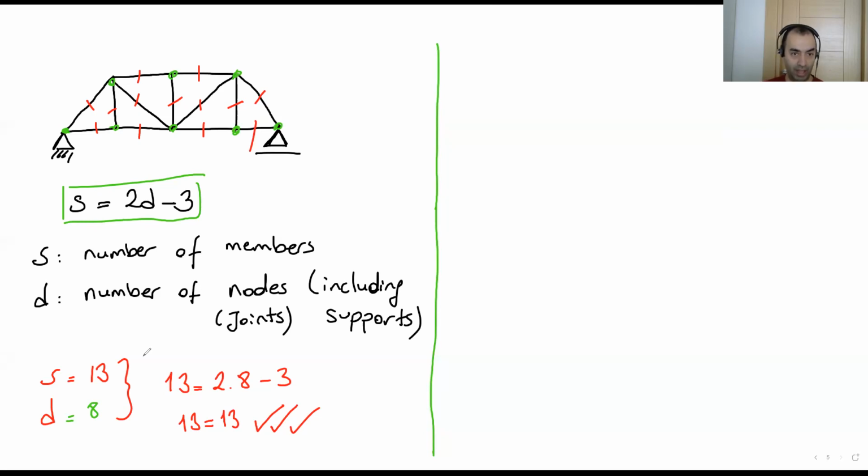There is only axial load on these members according to our assumption, our rule. That's why we only apply our loads to these nodes or joints. We never accept as an engineer to apply a load to the midpoint of these members.